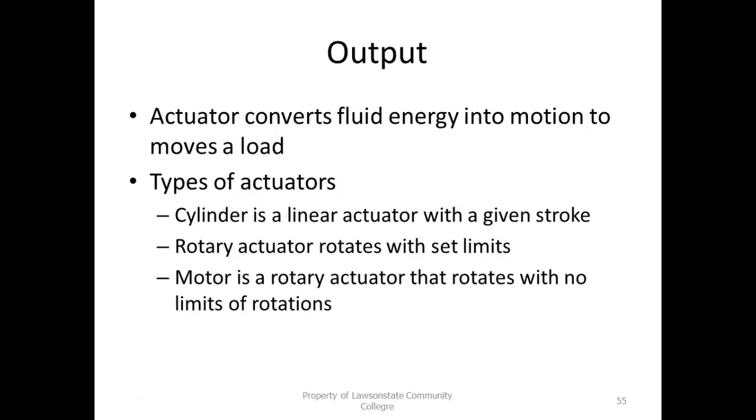Now we can reduce that by using what we call mechanical stops or variable stops, where we have something that the actuator hits. So you use a motor in your car door locks, but it's got a mechanical limit on the outside of the motor, right? You understand the difference. When the door unlocks, it cuts the power off to the motor and also stops it. But there's no limit of rotation inside. So a rotary actuator rotates to a limit, right? You understand that? And this is done by the mechanics inside the actuator.